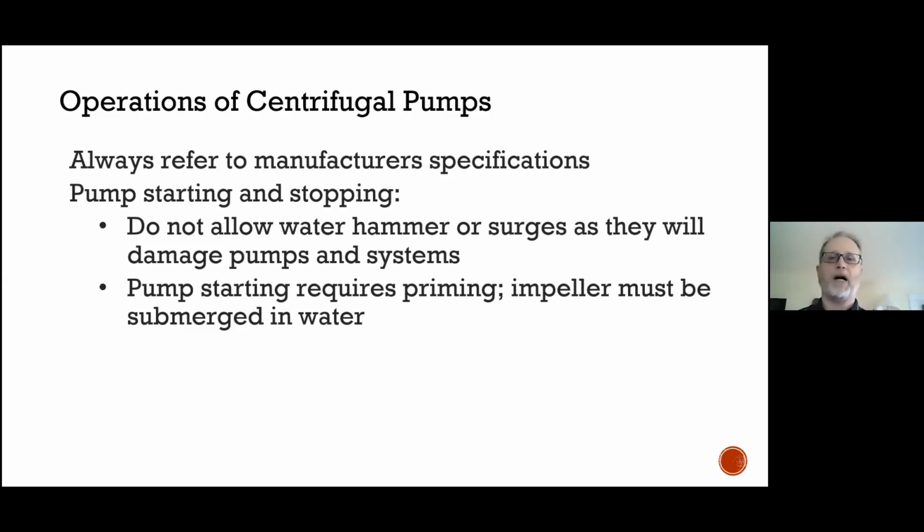So we either do that by variable speeds, slowly starting the motor and winding the motor up, or by closing the discharge valve. And when we were looking at different valves, we looked at globe and butterfly valves as good candidates to be used in that application, because we can close them, put an actuator on it, and open it very gradually to smooth out the profile of the water column moving up into the elevated zone.